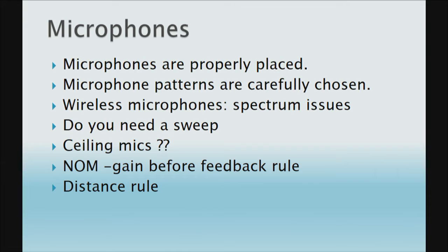And just a couple general rules. They've been around for years, and if you're a live sound guy, you probably know all these, but some people just never thought about this. I call it the NOM, number of open mics rule. There's a mathematical relationship. Every time I open another live mic on a live system, my gain before feedback is halved. Do that a few times, and what are you dealing with?